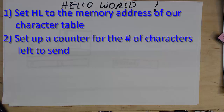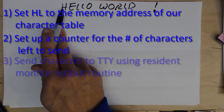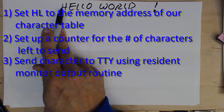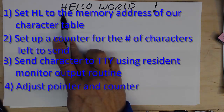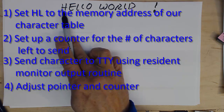When we have our loop, we're going to get our character, and then send that character out to the teletype, or in this case to the terminal program that we're using. We will use a routine that is already built into the Monitor 8 program. So we'll get that character, and then output it to the teletype using the resident monitor. We then increment HL so that we point to the next memory location, and we decrement our counter because we got one character done.